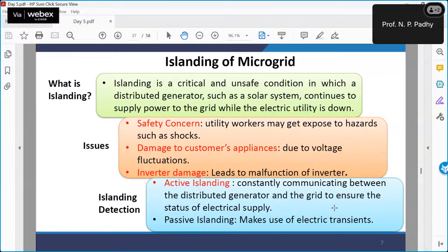Having our own resources, still we are not able to survive, because diesel generators we can manage anyway. But when the grid is not there, even your renewable energy, especially PV, stops generating, am I right? Because there is no reference voltage point for that.